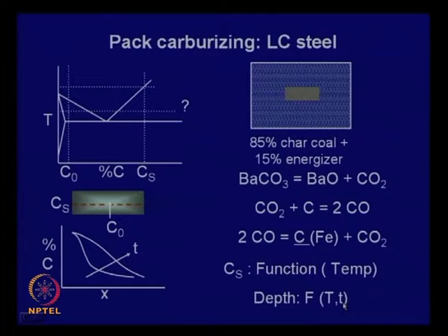Now, the question comes, to what temperature will you heat it? Suppose you heat it to a lower temperature over here. Now the problem is that at this low temperature, the solubility of carbon in ferrite in this region is very low. So, ferrite can hold only a very limited amount, possibly less than the carbon content which is already there.